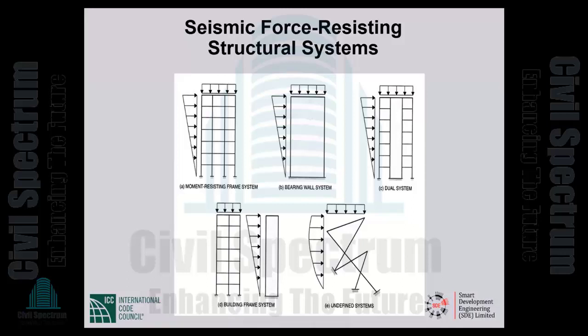The structure decides. If you do a proper interactive analysis of the combined structural system under lateral forces, you will see that near the bottom of the structure, almost the entire base shear goes to the shear walls with nothing carried by the frames. And as you go up, the frames pick up more and more, with the shear walls unloading on the frames. Okay, you have to design the frames and the shear walls on the basis of that interactive analysis. They will take different percentages of story shear on the different floor levels.